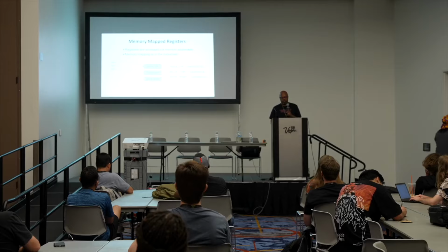Okay. Now, registers are memory mapped. What that means is that in order to write to a register, you write to a memory address. Every one of these registers is mapped to an address in memory, which you will find, again, in the data sheet or reference manual, whatever it is. In the data sheet, it'll say, oh, GPIO-A output data register is at address whatever. And then all you do to write to that register is you write to that address.